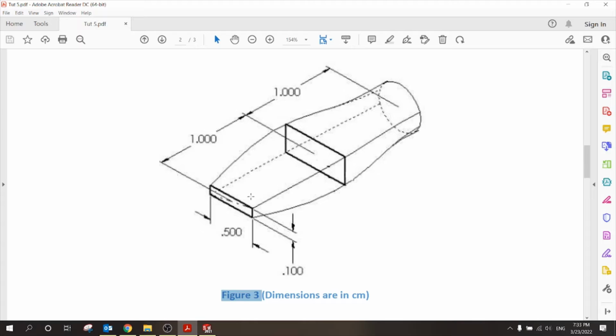For example, assume that I have a specific rectangle with dimensions of 0.5 length and height 0.1. But I want to end the extrude with a big rectangle, any scale. So I will make the rectangle, and parallel to that plane, I will create a new plane at a distance of 1, and I'll make the big rectangle, and I'll say loft.